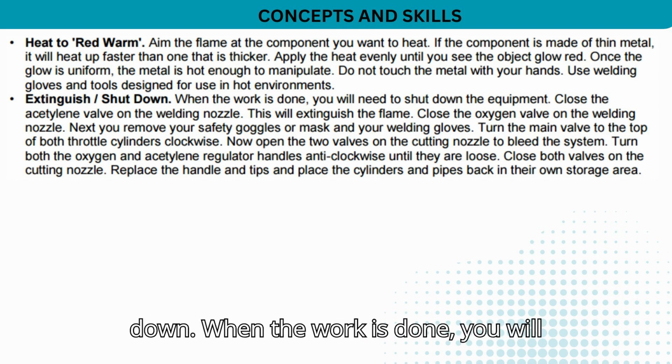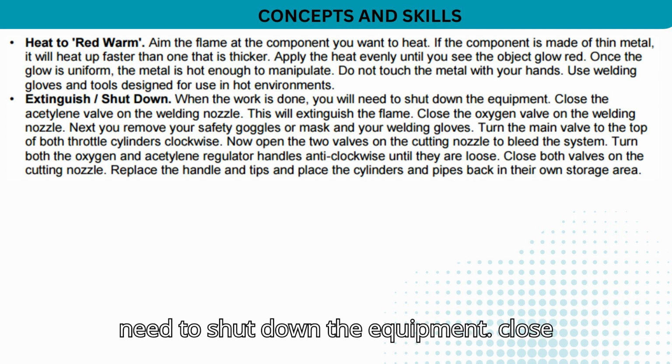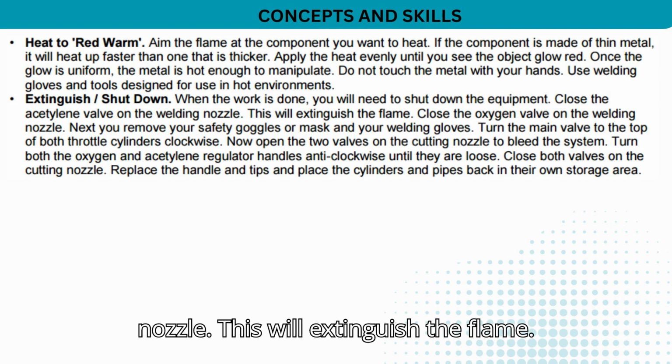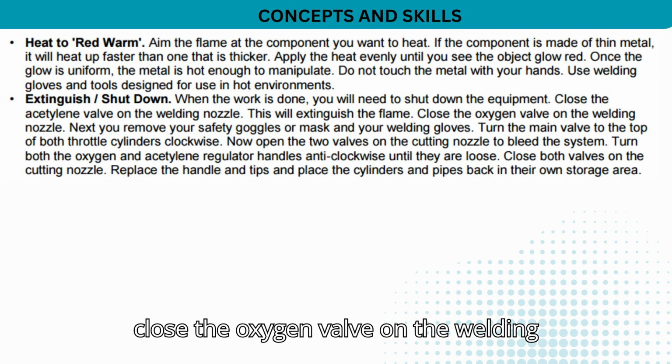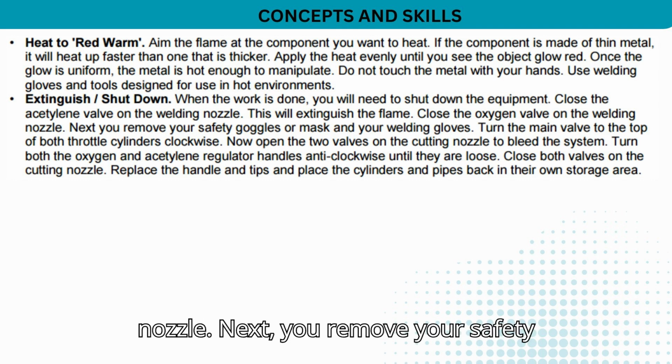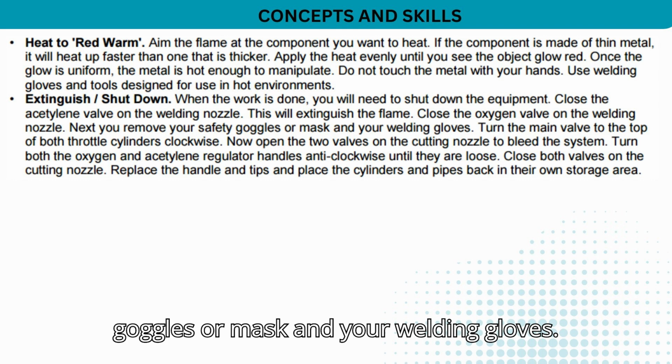Extinguish/shut down. When the work is done, you will need to shut down the equipment. Close the acetylene valve on the welding nozzle. This will extinguish the flame. Close the oxygen valve on the welding nozzle. Next, remove your safety goggles or mask and your welding gloves.